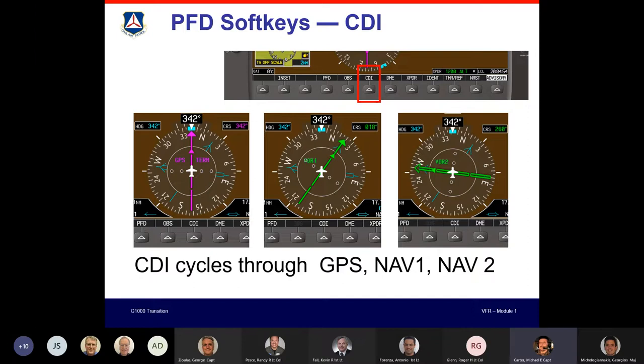So in the middle one, we're obviously using VOR1. That's why the needle's green, and therefore VOR2 is in the background in blue there. Because you can't use them both at the same time in CDI. If you notice, RMI1 is also there. It's behind the green. But I think you've got it. I think all answers were pretty much on.